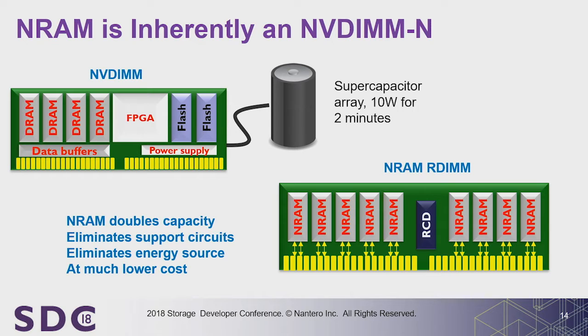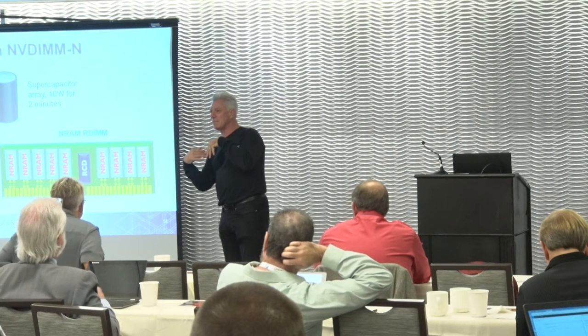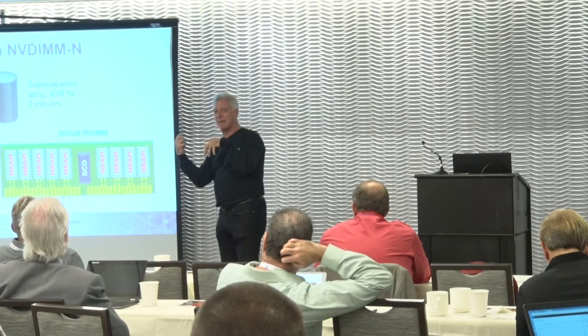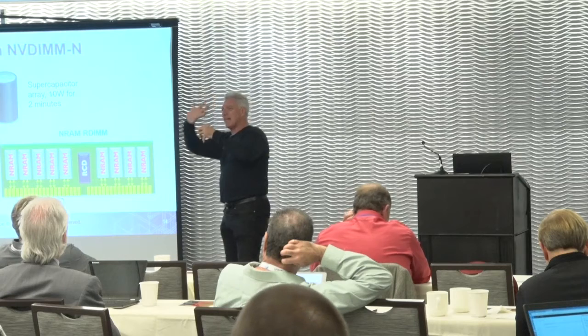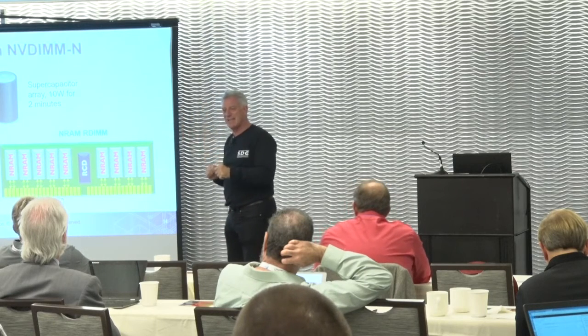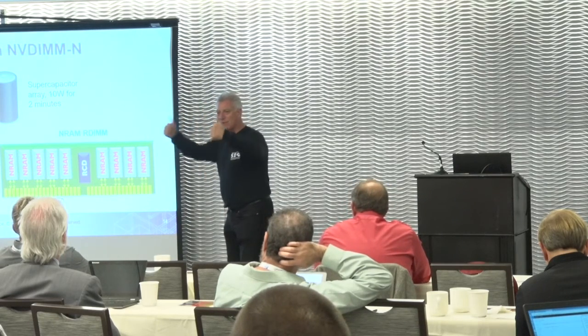So the cool thing about the NVDIMM is that you have this FPGA that's going to sit there and do nothing except burn power while you're exercising the DRAM that's on that memory module. And then on the back of the module, just in case power fails, you're going to disconnect that module from the system and take all the contents of the DRAM and save it in flash. And then power comes back, and you take the contents of the flash and load it back into the DRAM, and then you tell the system, let's rock and roll, dudes.